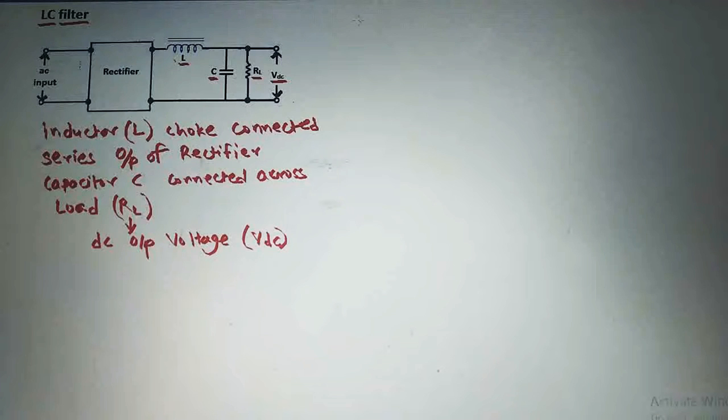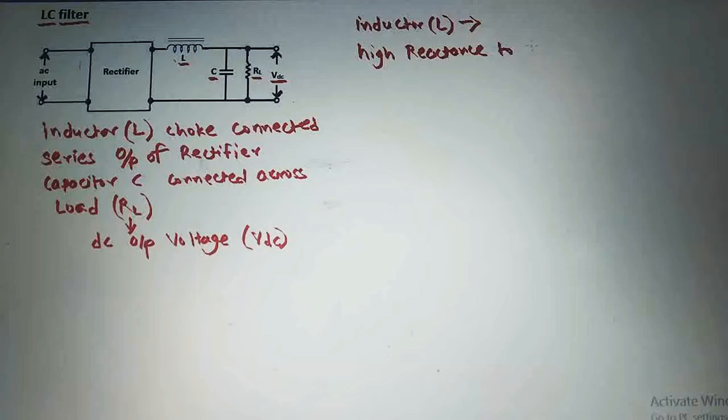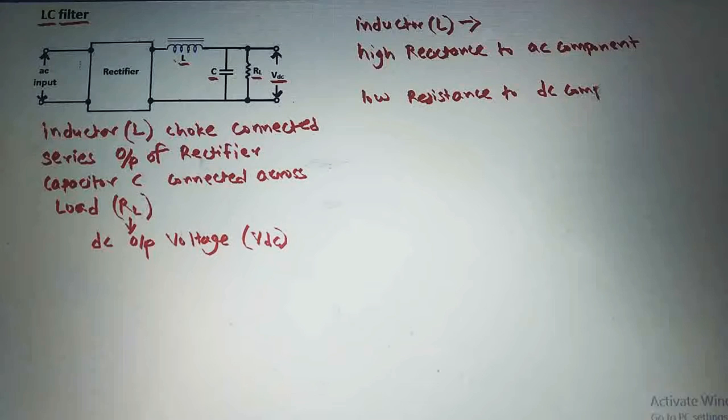See here, as this inductor L is connected in series with the output of rectifier, this inductor offers high reactance to the AC component, and it will have a low resistance to the DC component.